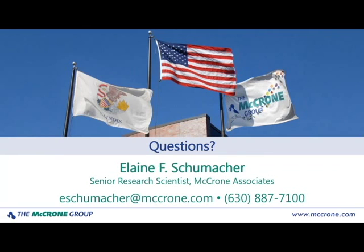And I would say that here at McCrone, typically the methodologies are the basic ones that I've described, which will be visual and stereoscopic examination, liquid in products, and then filtration and examination of filters, and then analysis with SEM EDS. Those will typically take you most of the way in determining whether you've got extensive delamination going on or not. Whether you're going to catch very early delamination, or something that may not delaminate as severely as quickly, it's difficult to say, but certainly in many, many cases, the PLM and the SEM EDS are enough to verify what you have going on.